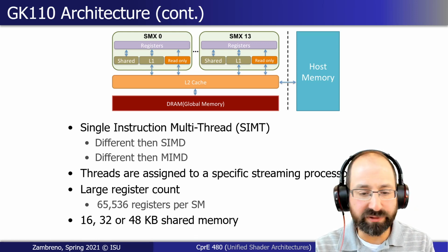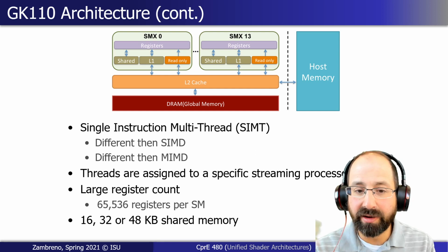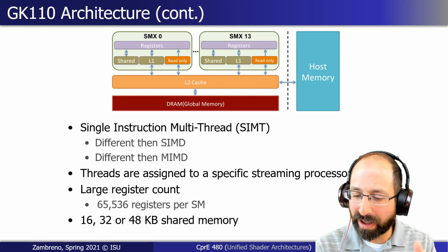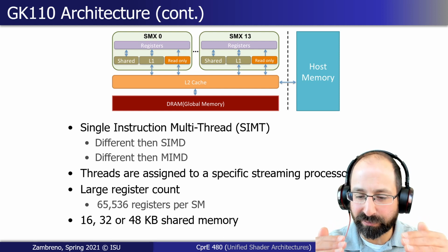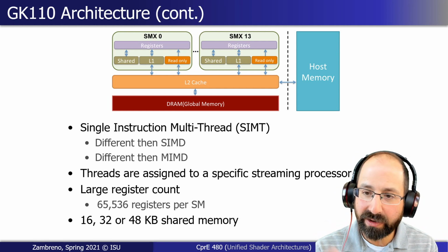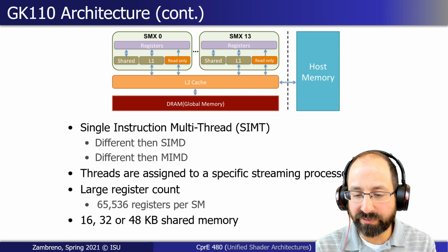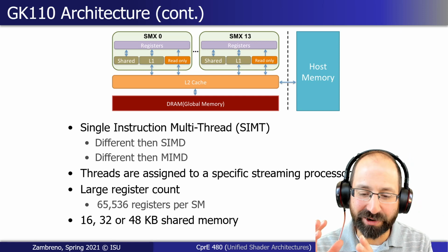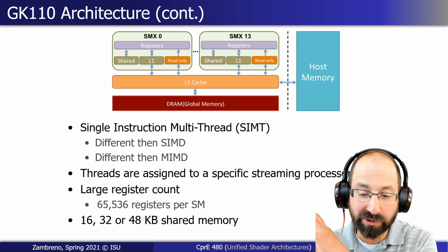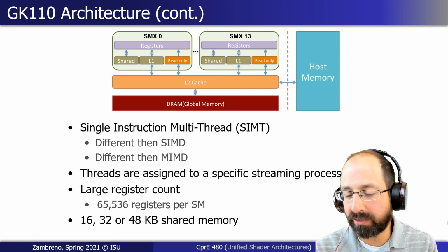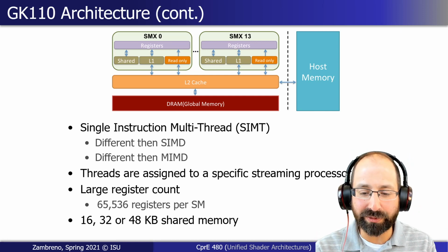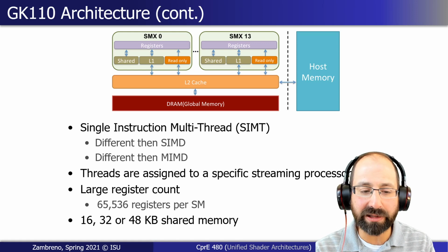Certainly, if they're all executing the same instruction stream, our instruction cache performance should be extremely good, right? Every instruction from the different threads is executing effectively in lockstep, so we get simplifying assumptions like having just one shared program counter for a grouping of threads, and a very effective instruction cache. You'll see for GPU workloads, instruction cache hit rates of 99.8% are very common. It's not an unusual or outlier thing.